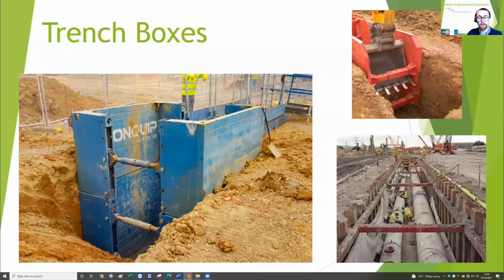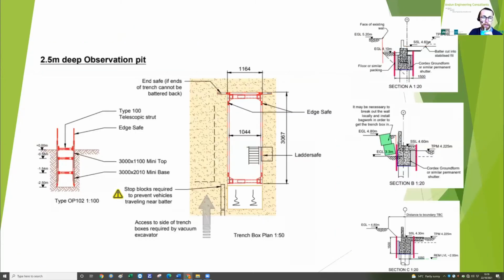They comprise prefabricated units that are lifted in and out of the trench as necessary, or they can be individual sheets, sheet piles and struts and walings, as I've mentioned before. So a couple of examples here. They must, by their very nature, be reusable. Because they're temporary structures, their appearance is irrelevant, really. Buildability is essential and made easier with prefabricated units, such as trench boxes.